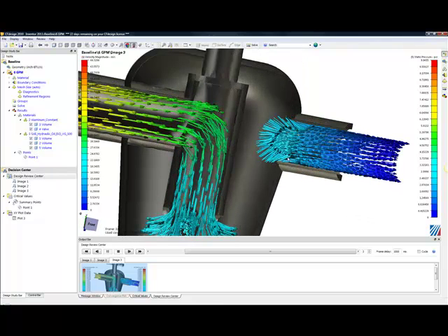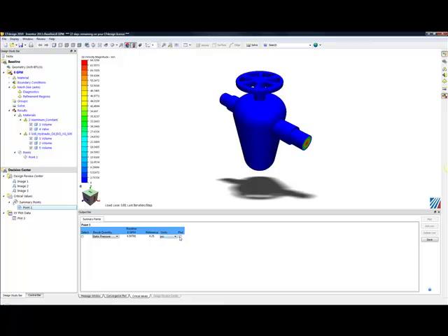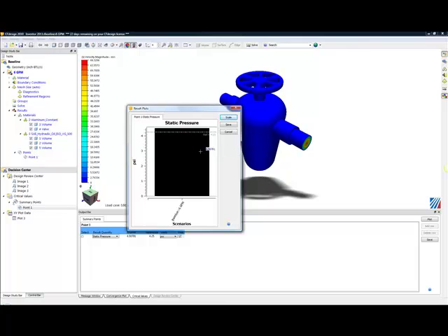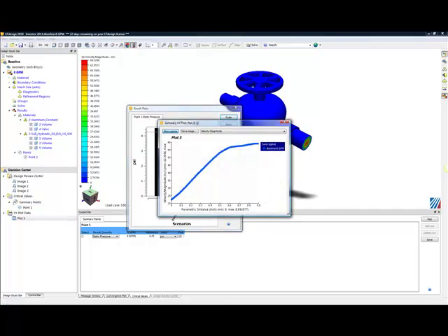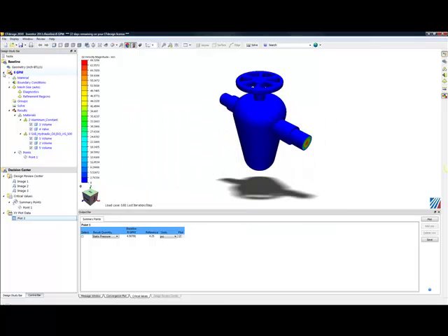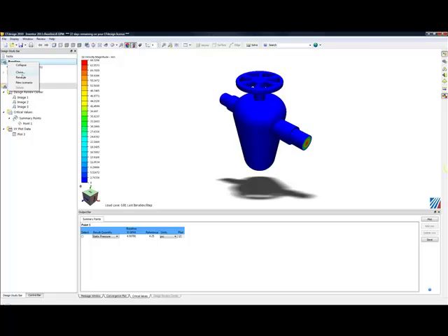In this case, the sharp corner at the exit is a potential problem. I have a critical value of 4.25 psi that can't be exceeded. I can see with a plot that the current design doesn't achieve that criteria. I can use an XY plot to look at the velocity magnitude through that section and also the pressure drop through that section. Once it's been determined to make a design change, I'm simply going to clone the current design.